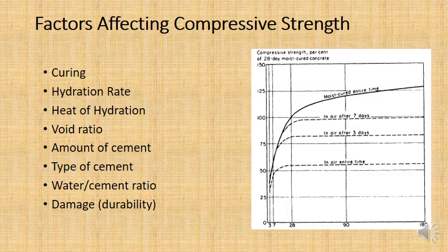Now, that excess water will eventually evaporate and leave voids in the concrete, weakening the concrete. However, that excess water also gives workability to the concrete. And so that's one of the big issues with making concrete.